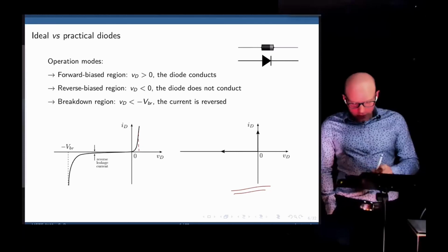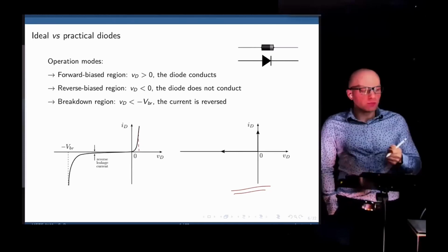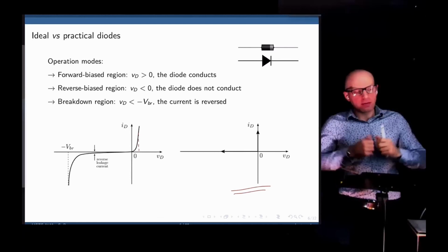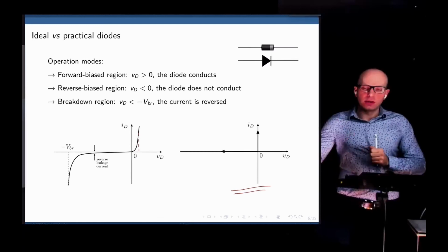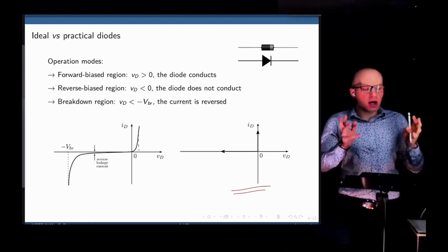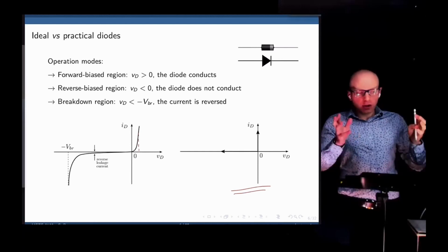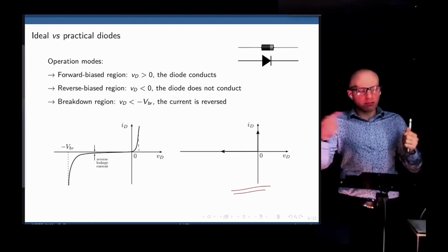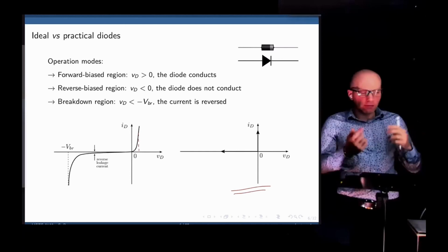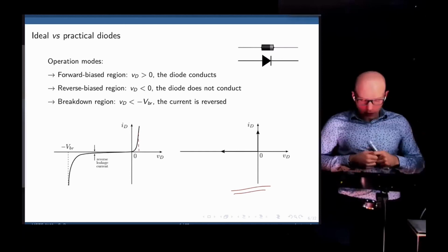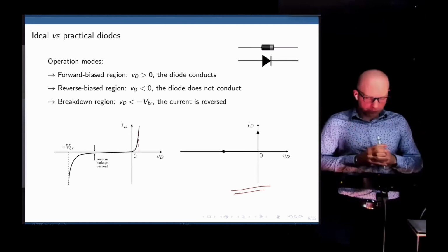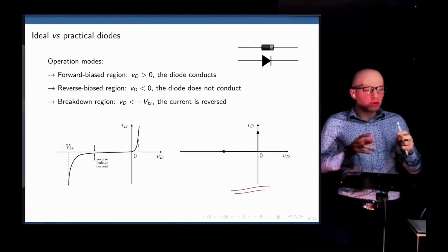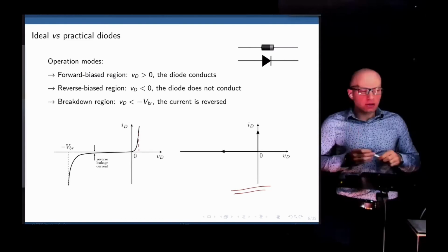If you think back on the valve analogy, the pressure would be so high that the valve would break down and allow flow in the direction of pressure, even if it's reverse biased. That remains for a while, but once the voltage is removed, after a certain time, the diode goes back to its original working principle.